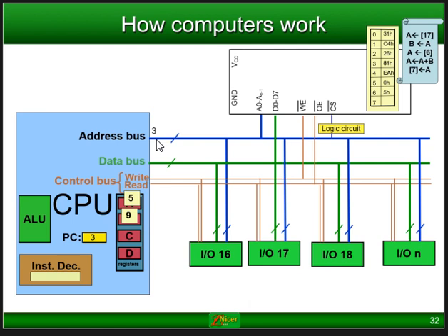There it's placing on the address bus number 3. So it will go to number 3, which is 81, which means nothing to us, but what it actually means is, once it's collected it, let's just see how it's collected. There it's collecting the instruction, and that instruction says you must add A and B. So this 5 and 9 must be added.